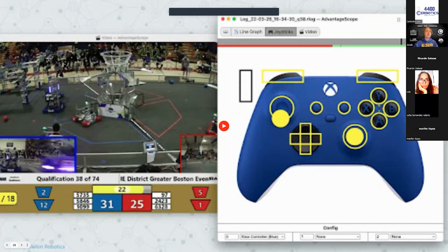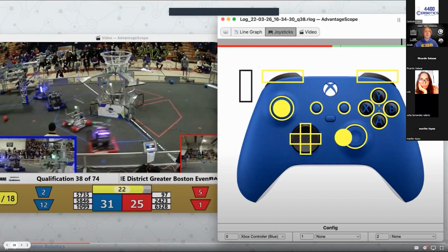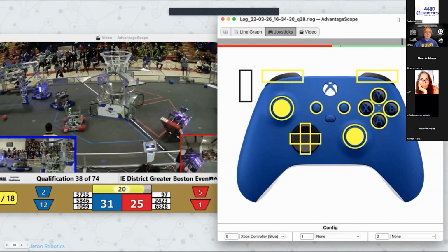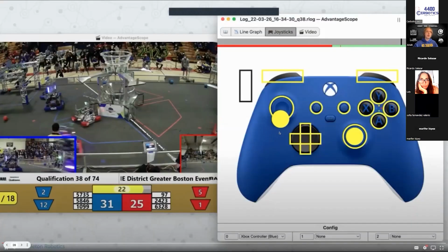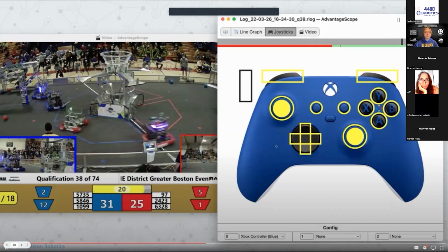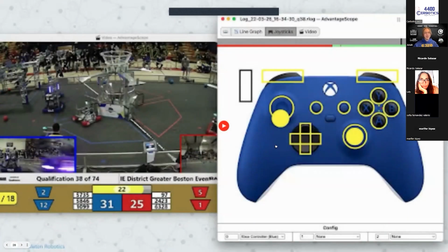I'm going to replay this at 25% speed. So we're running back to the hangar, and then, oh dear. The robot falls over and we stayed down for the rest of the match. I'm going to replay this and make sure to pay attention to what the joystick is doing. We're going backwards, and then as soon as we hit the cable bump, the driver releases the joystick. Of course, the top of the robot keeps moving when we land with the wheels, and the wheels are not turning. So we immediately tip over.